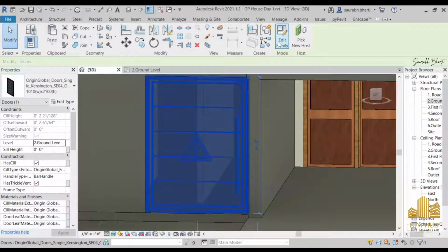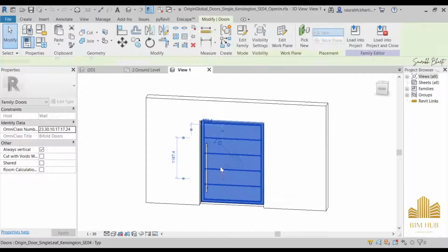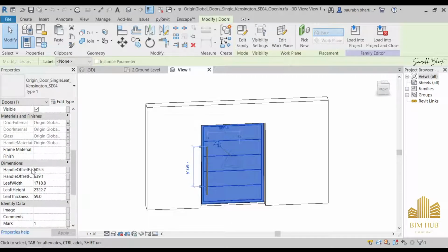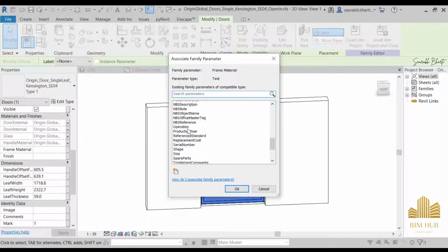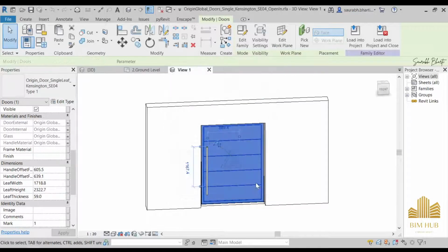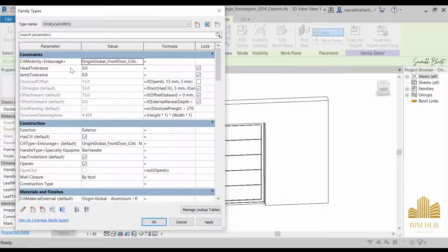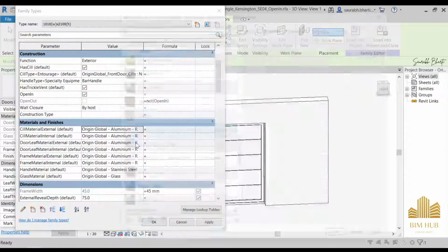And if I can't find it here, just go to edit family, and in edit family select this one, and here we can find material. So in this finished material, okay, these are the names of the material. That is huge. So let me go to it, and here if I can find some material, as you can see we have a material over this place.